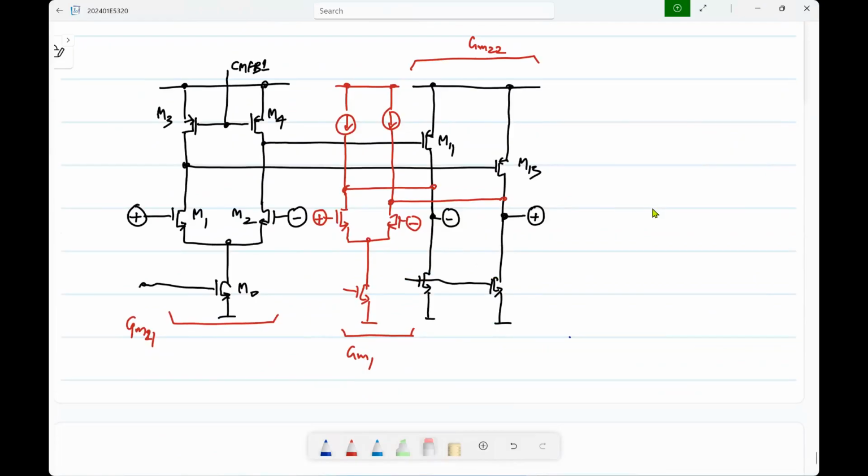What is another advantage of the two-stage topology that we had? Bandwidth? Okay. In fact, bandwidth wise, the feed forward is advantageous, right? It's better. Right. Here also you can do that. Because, I mean, you still have only, you stabilize either the first stage or the second stage output.